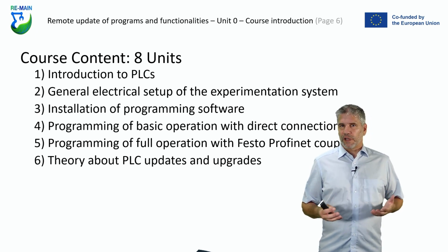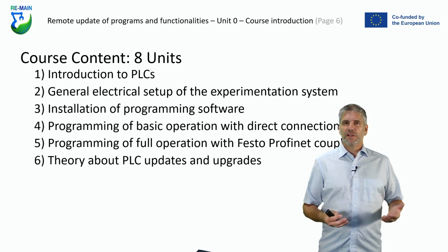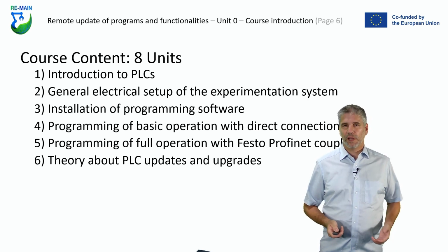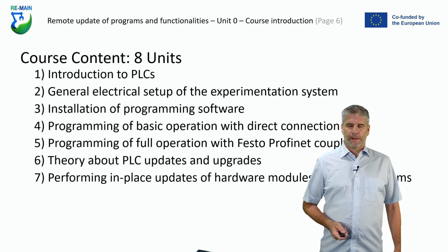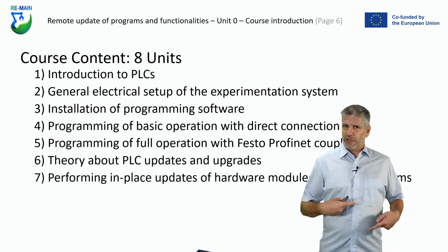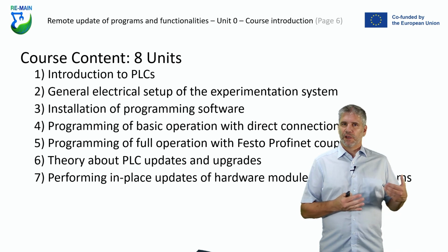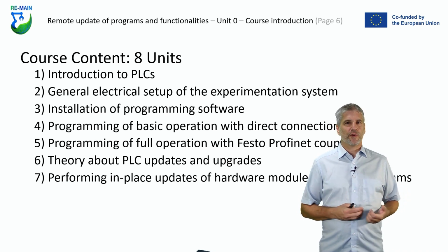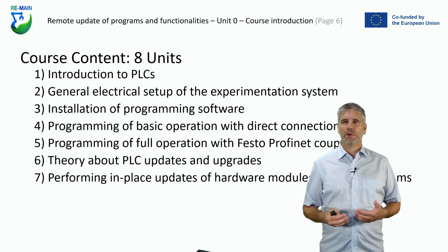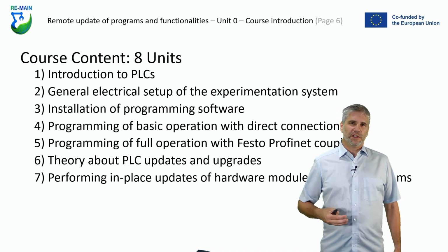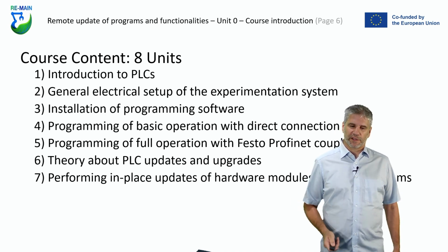And there's also a lot of danger because we may interrupt a working machine, which could lead to serious harm of people as well as of the machine equipment. And therefore, we have to deal with the different mechanisms that are available on PLCs. As to say, we have to update the hardware modules with new firmware, as well as we have to update software components, which can result in total reset or maybe can just take place during operation, just stopping for one cycle or a few cycles, depending on the machine, depending on the setup, depending on a lot of things that we would like to discuss in detail.